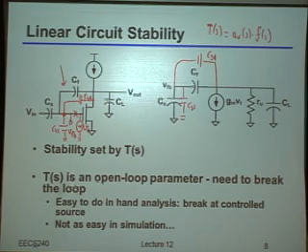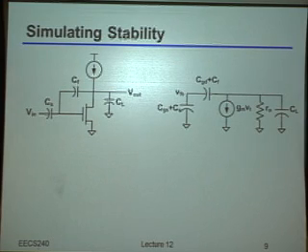Okay, just to make sure that's absolutely clear, notice this is the small signal model that we wanted, where the CGD ends up showing up in parallel with the CF, and the CGS ends up showing up in parallel with the CS.